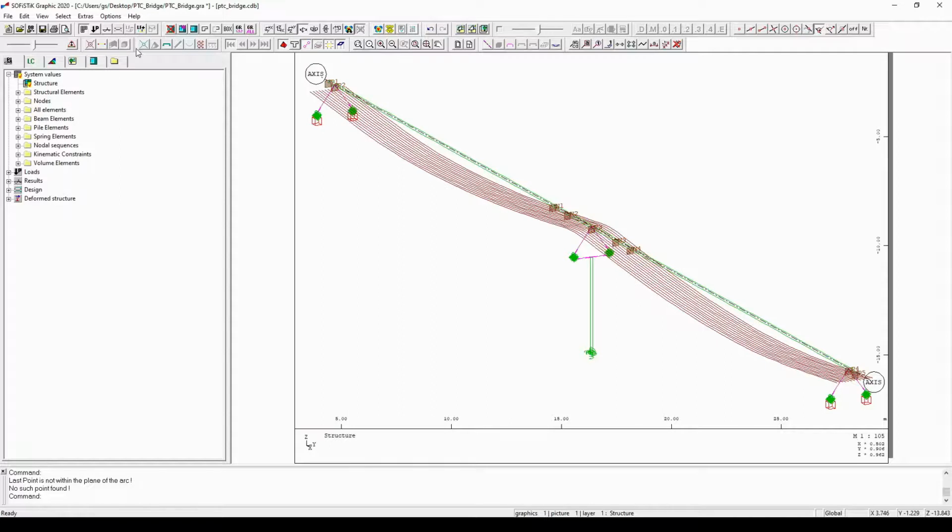It is also possible to search according to finite elements with the help of the finite element info toolbar, on which you will find some buttons that enable you to search according to finite element nodes, quad elements, beam elements. If we had truss elements in our system, we would be able to search for truss elements, cable elements, spring elements. They already exist in our system, therefore it is active to search. Then if we had boundary elements, we would be able to search for them.